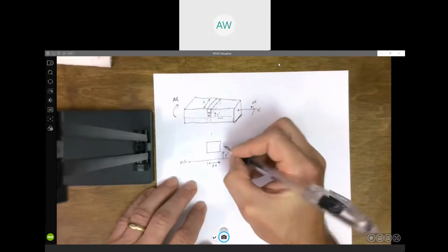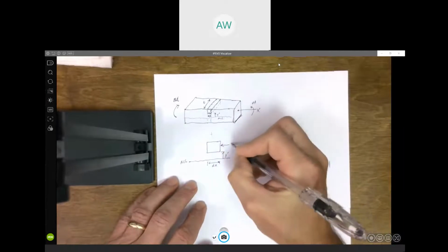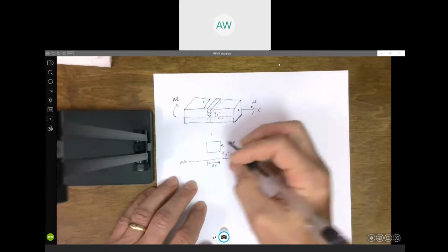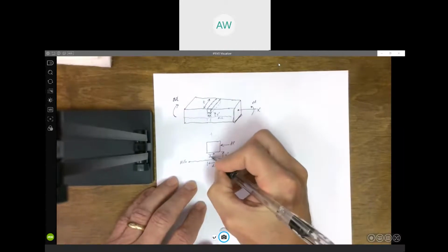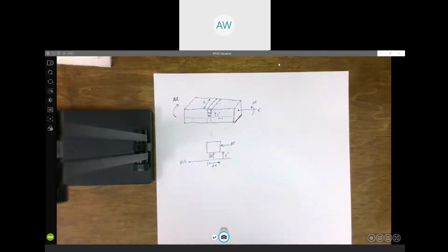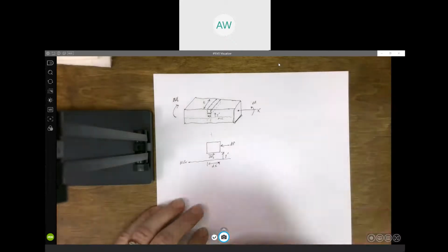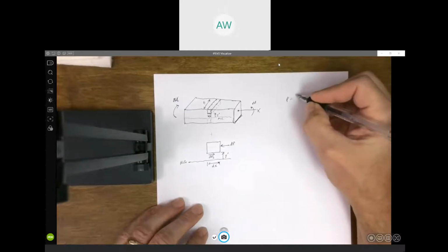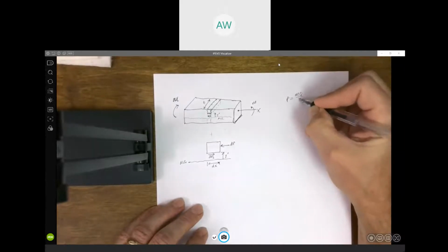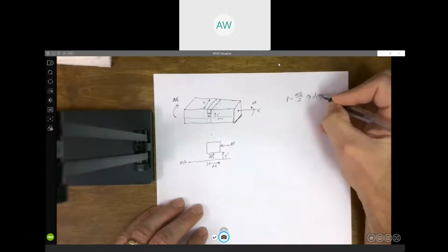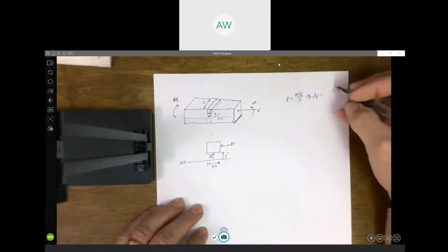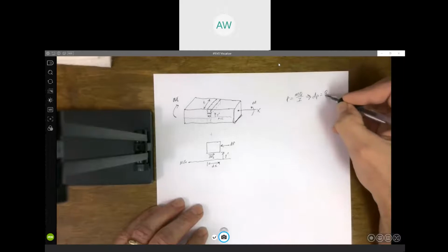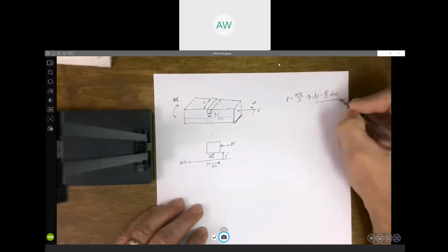And so we've got this differential force, we'll call it dP, and this differential shear force called dFs. Now, I saw on the previous page that the magnitude of P was M Q over I. So we'll go back: the differential force would be Q over I times the differential moment.